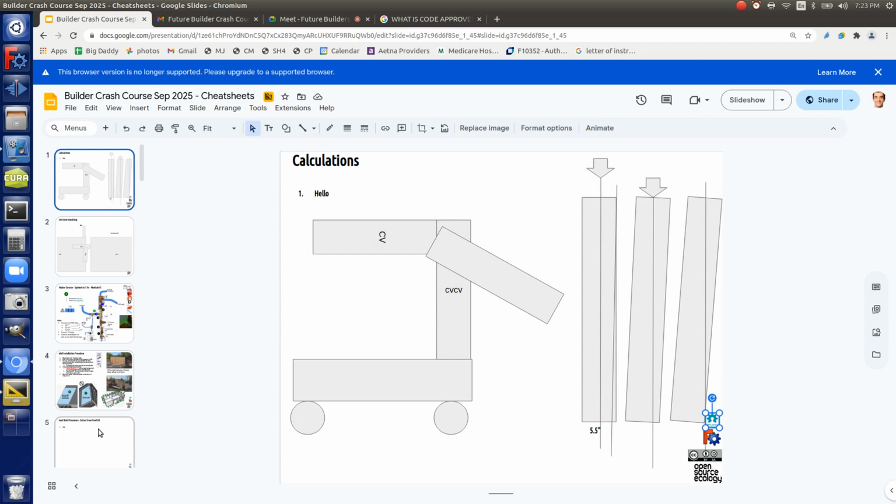Well, what's wood? OSB is around 300, they calculate. They do it at the lower limit of all woods, which are 300 to 1,000 or so, because OSB is just glued-together particleboard particles. So that foam, you can't do it. 25 is less than 300. First principles. No, it ain't gonna work.